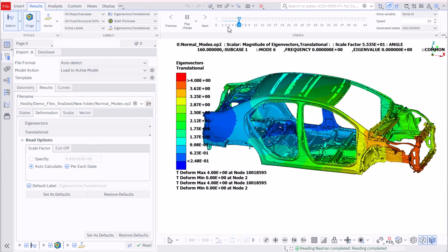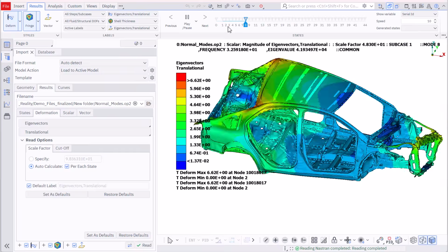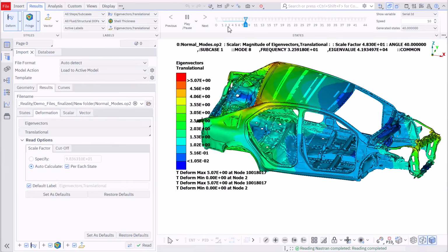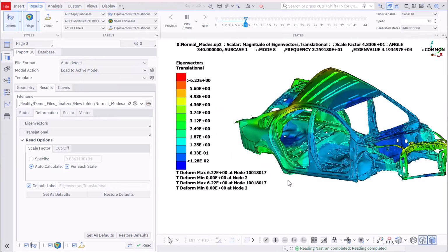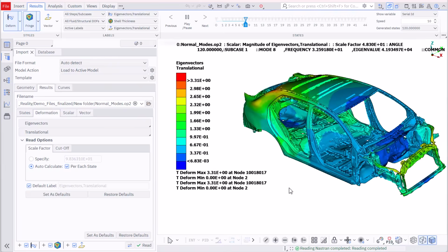As expected, the first 6 modes appear as rigid body modes, confirming that there are no unconnected parts in the model. We can also identify a torsional mode at approximately 32 Hz, which is not favorable for the car's design. However, thanks to the overlaying capabilities we demonstrated earlier, it is always possible to make corrections in ANSA and post-process the new results in no time.